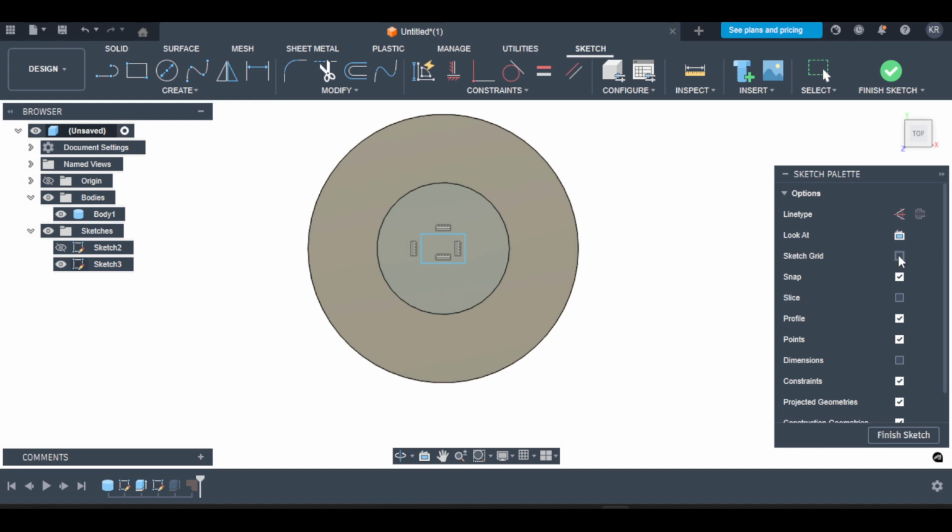If you're preparing a tutorial, a presentation, or a client review, this small adjustment can make your sketches look more polished and focused. A quick note on context: the Show Grid option in the sketch palette controls the grid when a sketch is active. If you don't see the grid changing, double check that you're actually in a sketch editing environment where the sketch palette is visible. Also remember that hiding the grid doesn't remove snapping options you may rely on. Your constraints and dimensions will still guide your geometry.